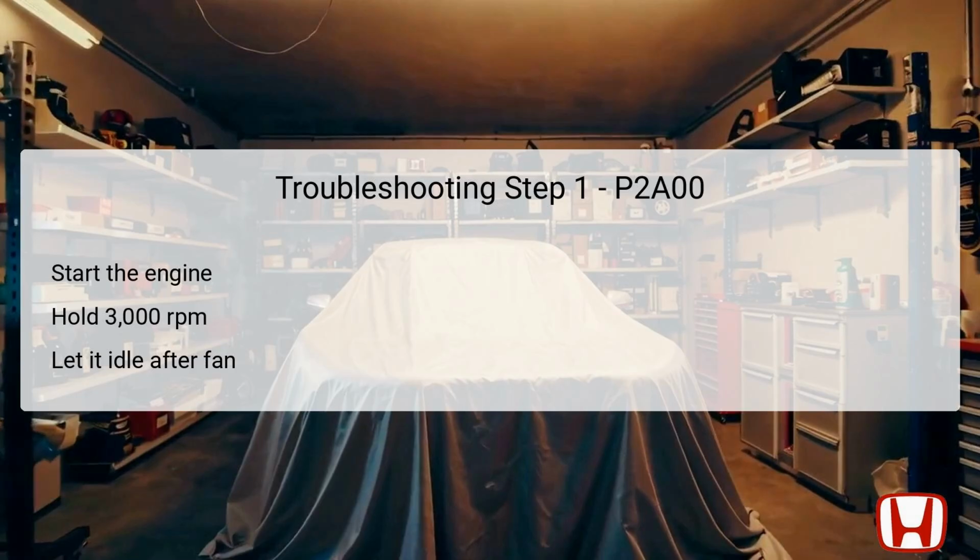Once the engine is running, it's crucial to hold the engine speed at 3,000 revolutions per minute (RPM) without any load, meaning the vehicle should be in park P or neutral N. This step is essential because it allows the engine and sensors to reach operating temperatures effectively. Observing the engine's behavior at this speed helps ensure that components like the AF sensor are active and responsive.